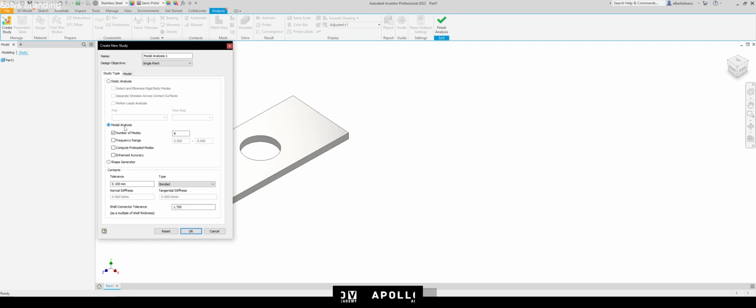So in this case here, let's say you've got a motor attached to this. You don't want the resonant frequency of this part matching up with the motor, because eventually it's going to create a lot of vibrations throughout the entire machine. Because every time the motor swings in one direction, all the atoms in this part also swing in that direction. And that's not very good, because eventually that whole thing is going to break apart.